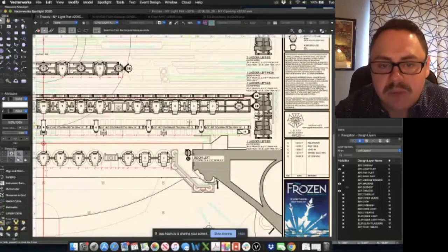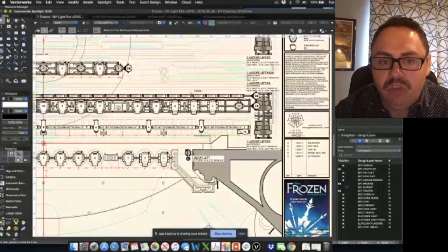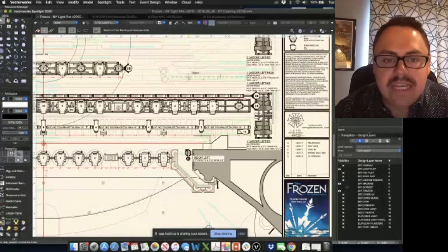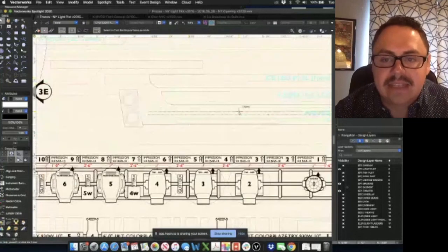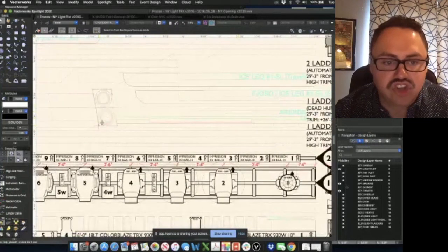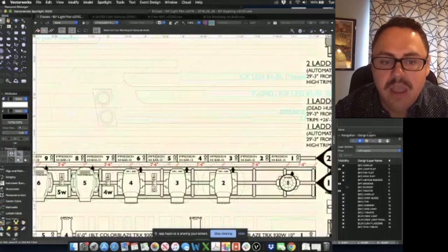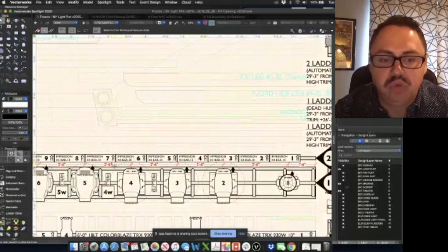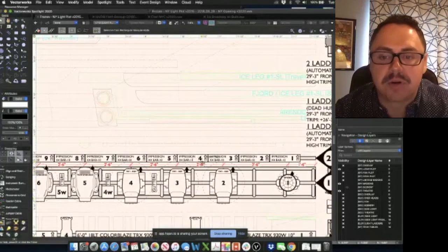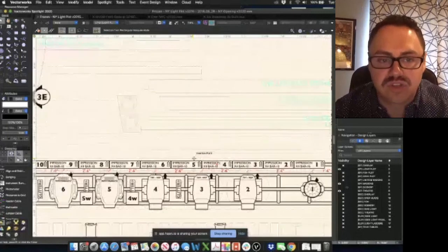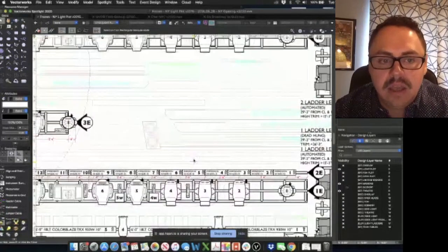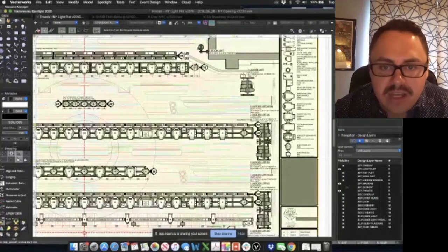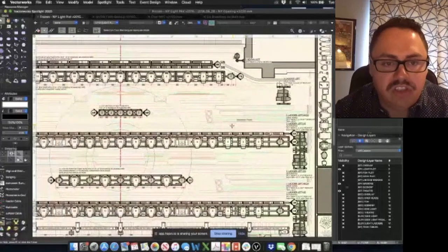Once again, I talked about that line weight and being the boldest thing on the paperwork. You can see here, I have very thin lines that show all the scenery and it shows the relationship to everything. But what's important to me is the lighting. So the lighting is much bolder. It's a much heavier line weight so that you really can see the purpose of this drawing, what it's used for and everything else. And those are kind of a lot of the things on the overheads.